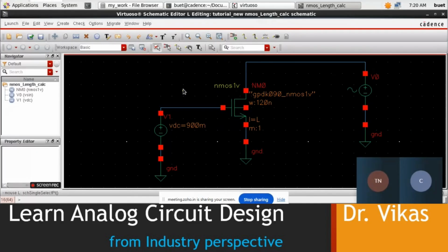And if I want to achieve that, I need to first figure out a particular length for which the output resistance of a MOSFET is very, very large. Whatever the value of L I get, for that L, the value of R should be very, very large. If I use that L in building my current source, then that current source will develop a constant current with a very large output resistance, because you have chosen the value of L according to the resistance you are calculating here.